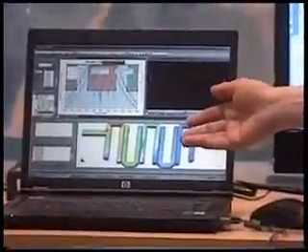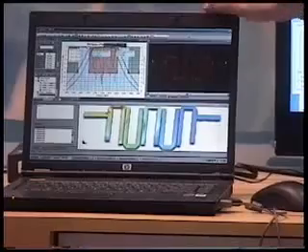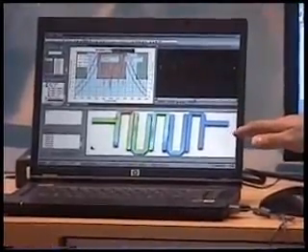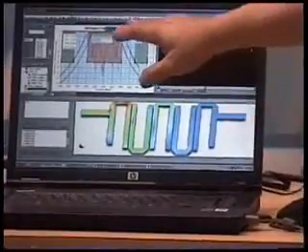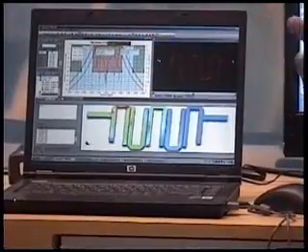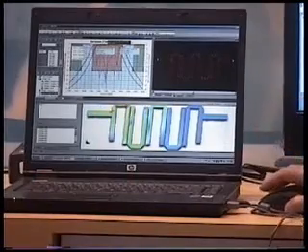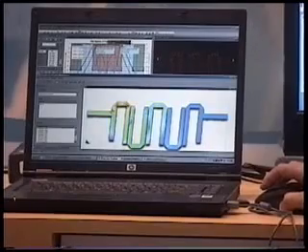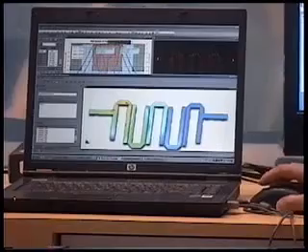So what you see here is a bandpass microwave filter synthesized in Genesys, laid out in Genesys automatically, and then we do the electromagnetic simulation on the layout to check on the performance, taking into account all of the higher order interactions that the synthesis equation does not directly calculate. In addition, you can also look at it in the 3D viewer that you have seen before. We can move and rotate the structure, and you can also look at the surface current flow.